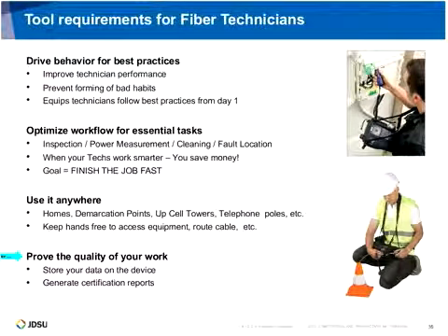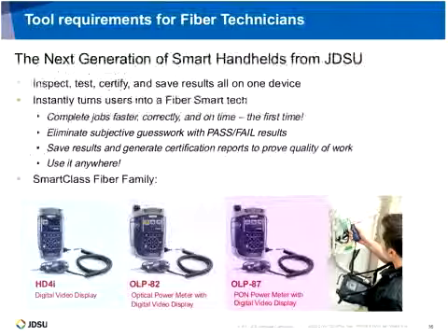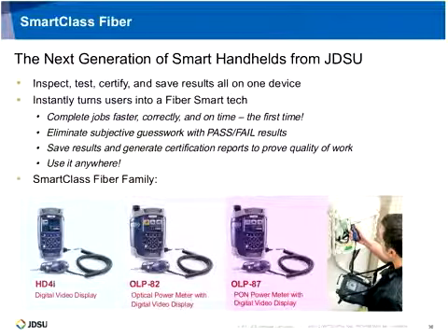One of the nice things with objective inspection tools is there are some perks that come along with it, in that it allows you to capture the interface of the connector. It'll drop in the overlay of the zones and also the defects and the contamination. It'll give a pass-fail report on that. And you can print out certification reports or create PDFs to provide to your customer in the end, as proof that the work you did and the job you accomplished is in compliance with 568C.